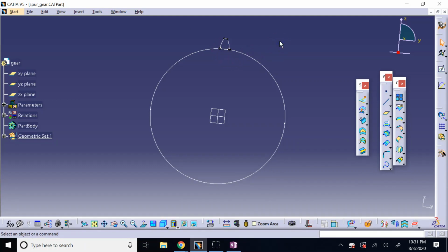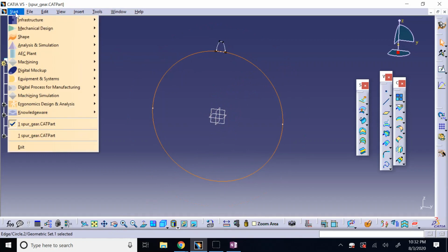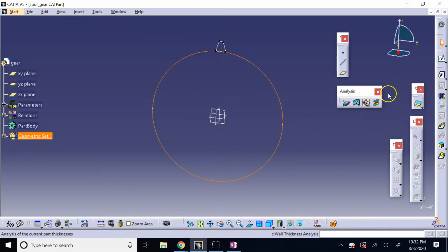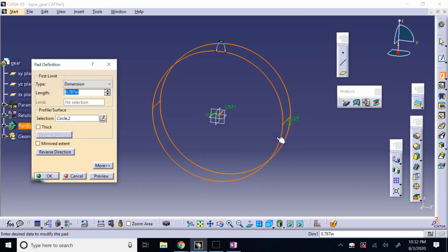Okay, so what you want to do is in each one of these sketches, each one of them you do a separate, so I can select this and extrude it, then I can select those guys. Of course I have to join them first, right? So for example here, if I choose just this guy, can I just go ahead and extrude it? So if I go to mechanical design, part design, can I just extrude that? Yes. And then you of course have to provide some width of the gear. Now here it is just asking to go for 1 inches, so you can go 1 inch.